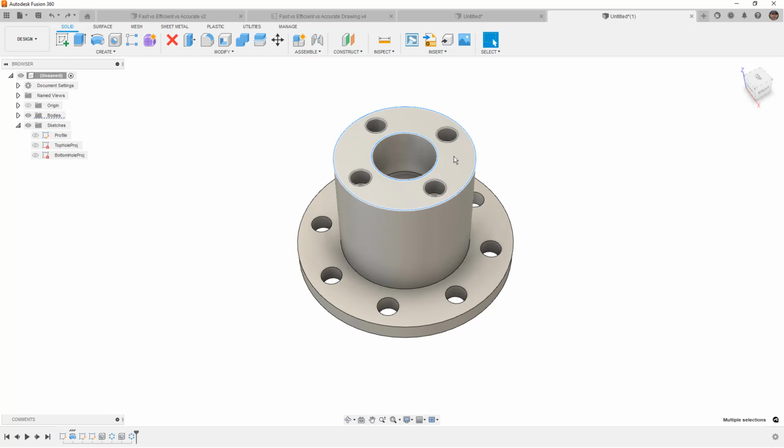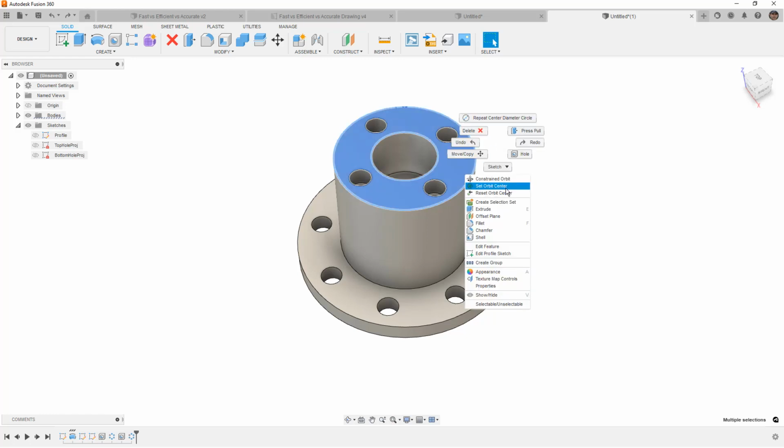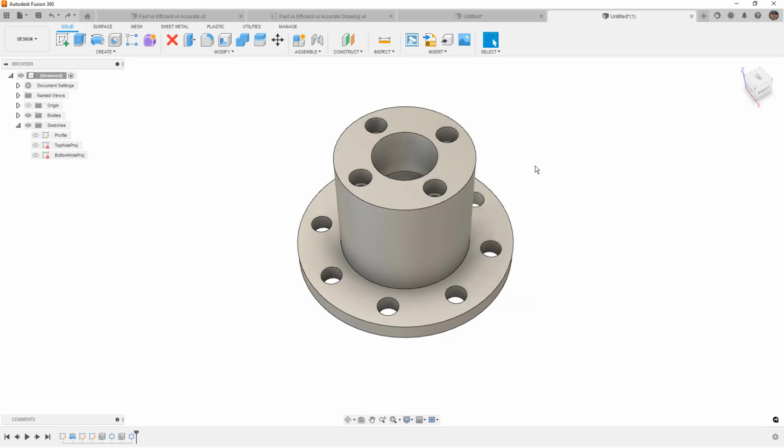We also, if we select a face in that, you'll notice that we have some options: extrude, fillet, chamfer, shell. This means that if we select extrude, it's going to drop off the edges. If we select fillet, it might be able to use the face and the edges. If we select chamfer, it'll drop the face and so on. Shell will drop the edges. So there are cases where understanding what tools will be available to you as soon as you use things like the right-click marking menu are going to be very helpful to being efficient and fast.